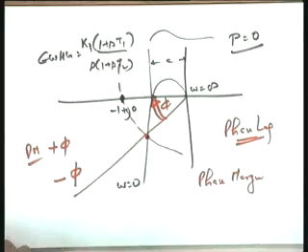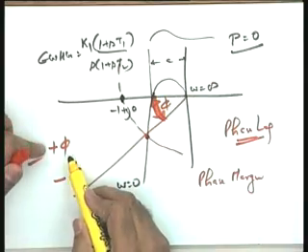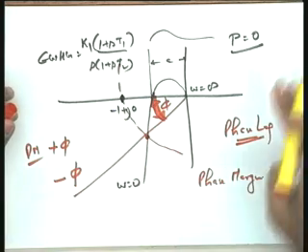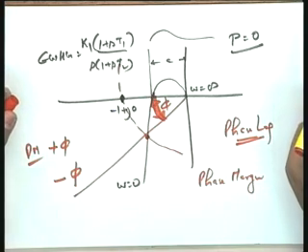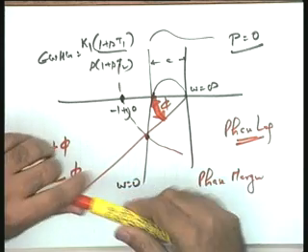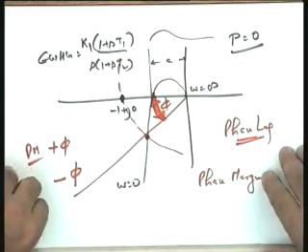You will please note that this phase margin is positive, because this much of phase margin you still have. If this much phase lag is added to the system, in that particular case the system goes to the point of instability. Hence these are the two measures, the gain margin and the phase margin, which represent the measure of relative stability using the Nyquist stability criterion, very important measures.